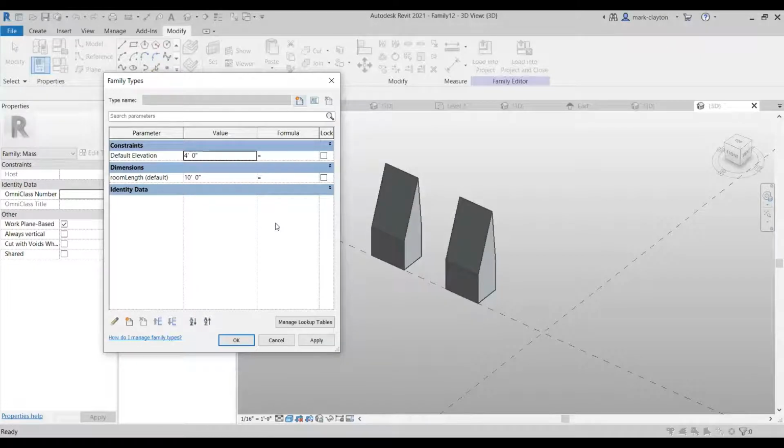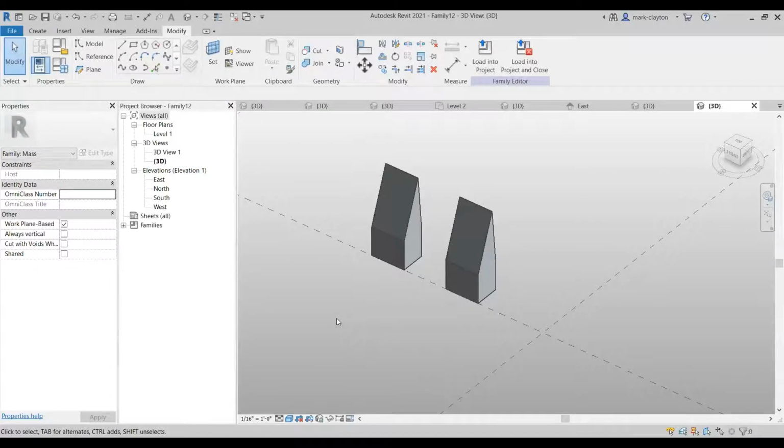And I can control the dimensions of the one room family by the dimensions of the dog trot family. And the notion of building up, trying to identify what the smallest component is, and then building up a library of families and nested families out of the same kind of component is where you start to create your own language of architecture.